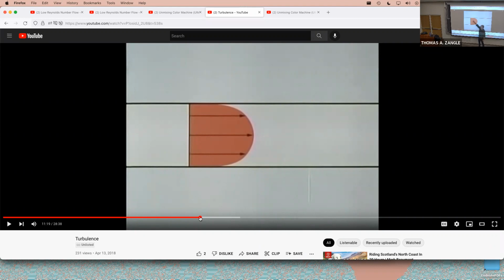So this we only understand on the basis of experimental data. When we're analyzing pipe flow or an engineering situation, we really just care about the time average velocity. Our major task is going to be figuring out what this velocity profile is, and therefore what the friction factor looks like for turbulent pipe flow. It's going to be different from laminar flow. All right, any other questions?